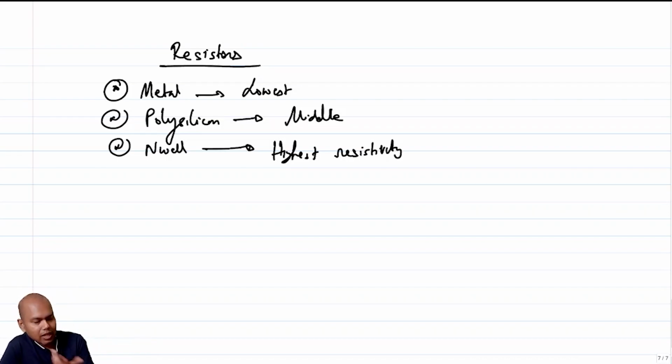If it's a semiconductor material, it is possible that with temperature increase, the resistivity decreases, because you have more and more carriers. For example, in some processes you get a resistor made of intrinsic silicon. You will see that as temperature increases, the resistance decreases. They have a negative temperature coefficient. But in most cases, even if you are using an N-well resistor or polysilicon resistor, you will see that as you increase the temperature, the resistivity increases.